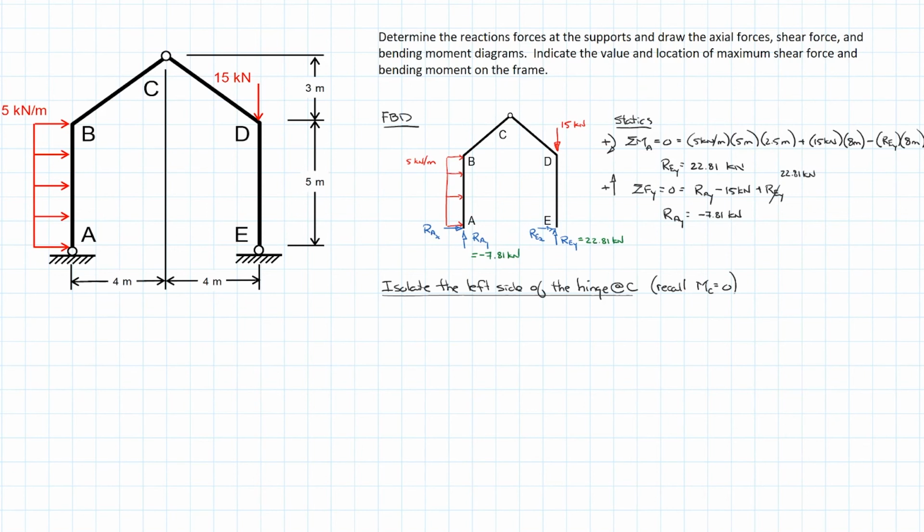So I'm just going to bring up my half section. Okay, I've pasted in my half section, so it's a free body diagram, so we're going to have to draw in what we know and don't know on it. So the first thing I can do is put in my reactions again at A. So we have reaction AX.